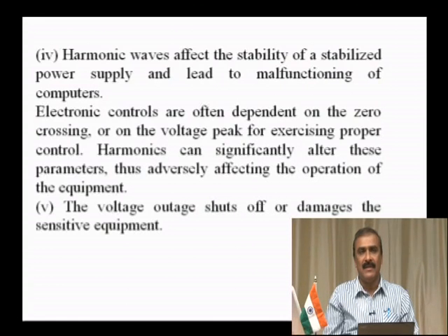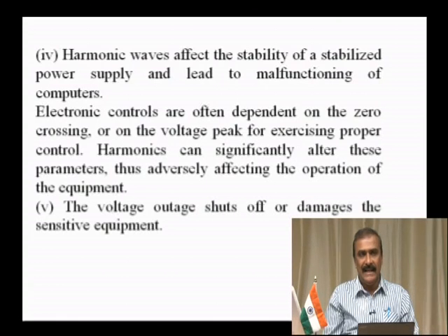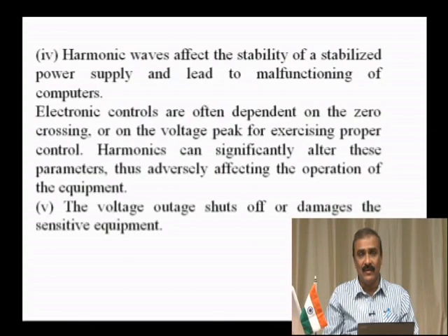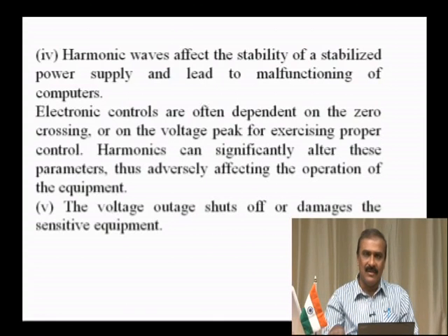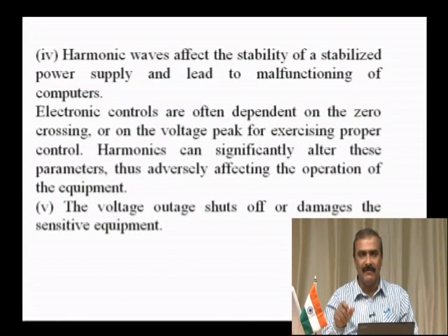You should not allow these harmonics to play with your system for your power supply. So, why? This is the reason. It disrupts the zero crossing of your original sine wave. So, once you have designed your commutation circuits or whatever circuits for power control, there will be a shift of this zero crossing line. Now, the moment this zero crossing shifts, definitely there is an error in the system. So, this electronic control will not happen as you desired or as you have designed the system.